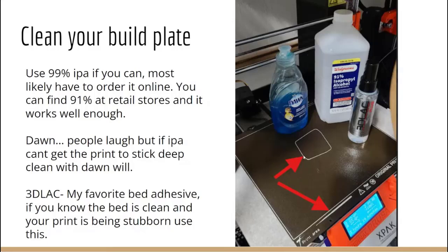But also, as you can see here with the red arrows, in your slicer settings, there's going to be a purge line, because you need to make sure there's plastic in the nozzle before you start printing. And then there might be some kind of draft shield or brim or skirt that goes around your print early on, and you've got to remove these before you just send a print to the printer again. So if you do have a network printer, this is even more important, because you're not standing in front of the printer when you start it. You need to make sure, right, that you go remove the physical things off the printer so your next print is available.